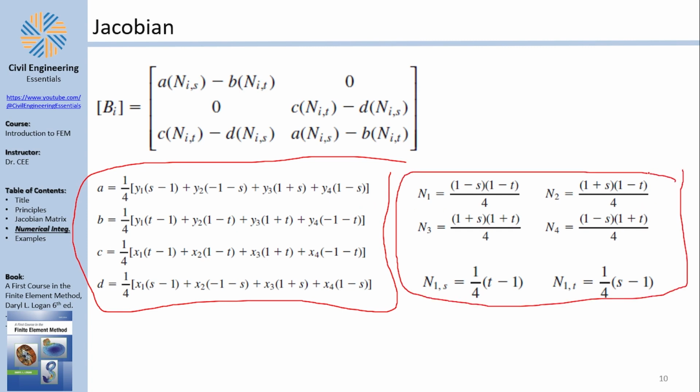You could call foul here and say, are those shape functions following the Pascal triangle? Well, yes, they are. Because the Pascal triangle says 1, x, y, and then x square, if you remember, xy, and y square. This is the Pascal triangle. I think it was in the linear strain triangle lecture. I'm not sure. Well, the number of terms you try to take is the number of degrees of freedom. If you have 4, you're going to use those terms. Now, in our case, we have S and T, so it's going to be 1, S, T, and ST.